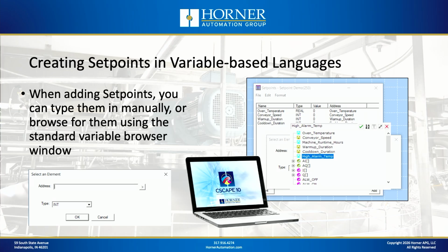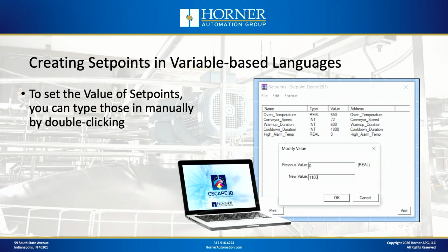Now you can either manually type them in, or you can use the variable browsing feature that's available in Cscape throughout to find the variables that you want to add to your Setpoint table. Once you've added the variables to the table, there's another step that's required. You need to type in or assign the known value to each of these variables that's in the Setpoint table. That's the whole point of the Setpoint values.